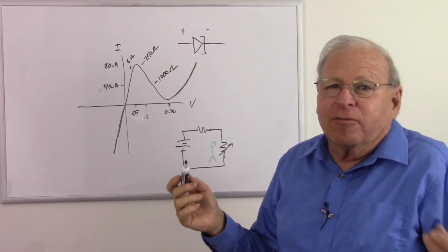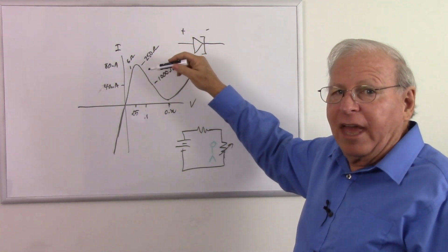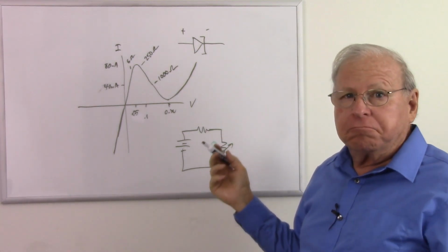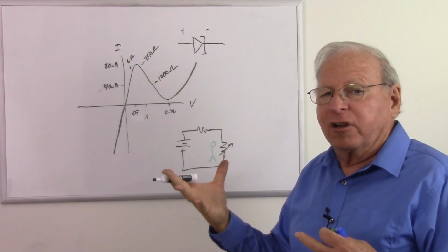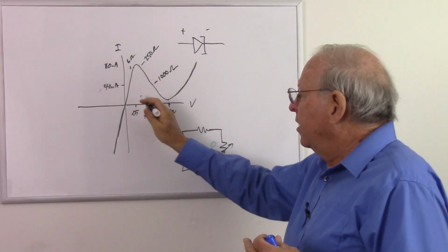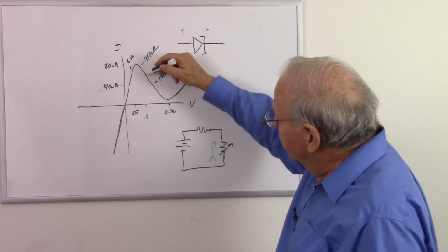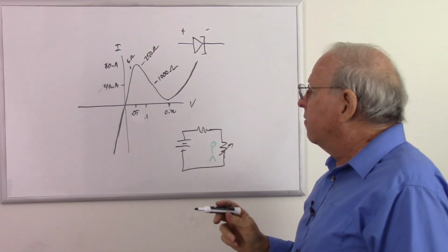Well, what is that? It just means that the little green man is increasing his resistance exponentially as our voltage goes up to force the current down. So that's just what the tunnel diode does. It increases its impedance exponentially as the voltage goes up between about 50 millivolts and about 0.3 volts, causing this anomaly here that we call negative resistance, and it follows that curve.